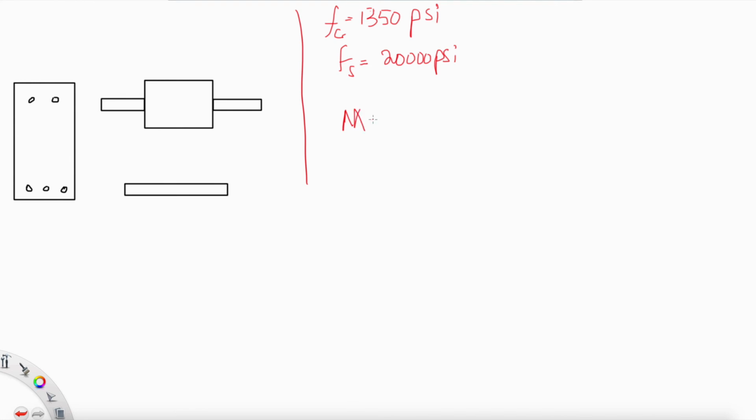Let's say the moment in concrete is the stress multiplied by the I, which is the one we computed previously, 0.67, over the 6.78, which is the centroid distance, multiplied by 12,000 as a conversion factor to kip-foot. Then we will have 67.5 k-foot.